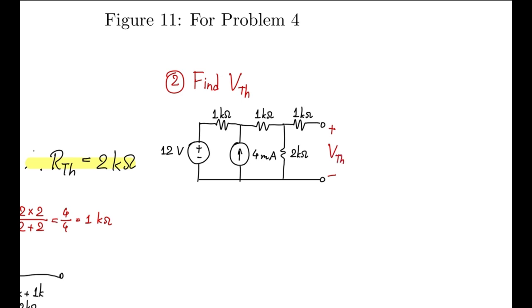Here, we may use any applicable theorems to help us find the voltage. In this case, we will use nodal analysis in tandem with Ohm's law. We start by finding all nodes in the redrawn circuit, then mark one as the reference node, or the ground node. Then, we denote unknown currents on each resistor with arbitrary directions.